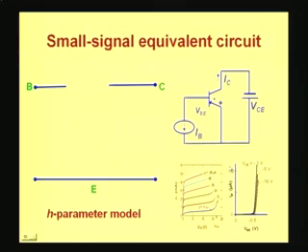Obviously, since we are deriving the equivalent circuit from DC characteristics, this equivalent circuit is valid for low frequencies. So generally the H parameter equivalent circuit is used for low frequencies. Some more justification of the use of the H parameter equivalent circuit will be discussed later when we take up the characteristics in detail.